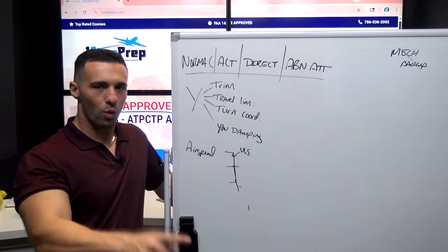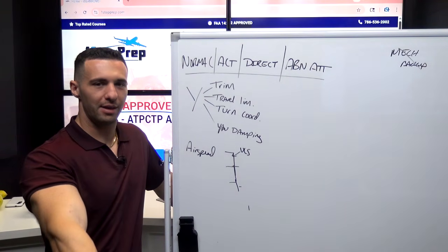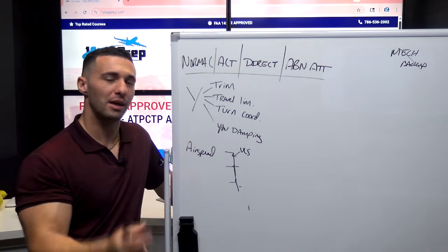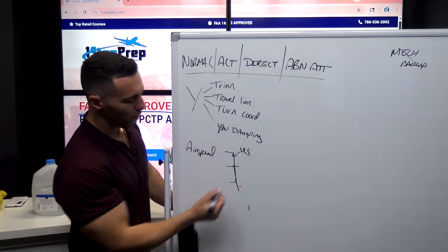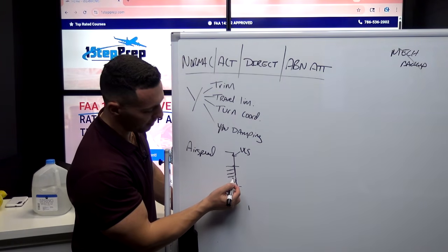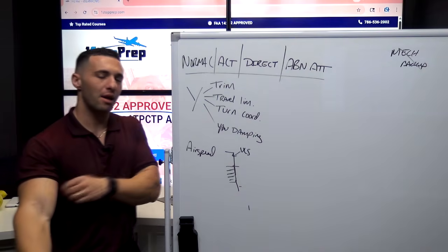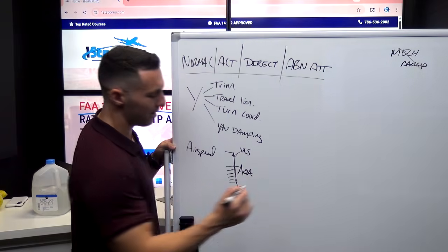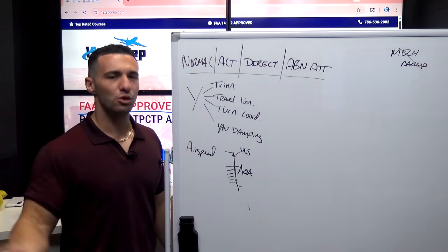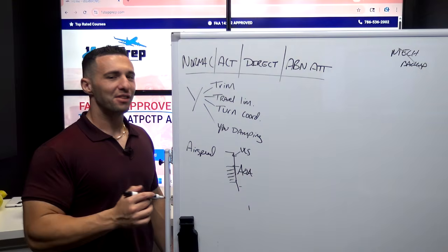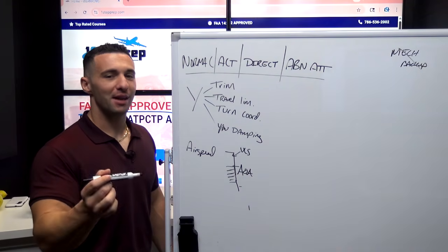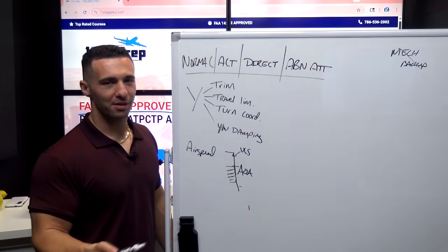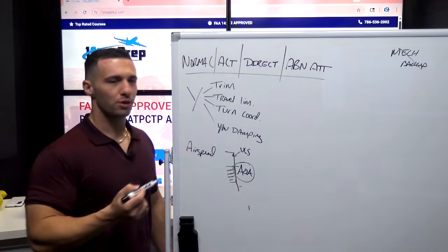So one is FMGC calculated down there, but the other one is a presentation being displayed by the FAC. To that degree, I want to share something else with you, which is that you also have alpha prot displayed here, which is kind of like these different dashed lines. And alpha prot, remember earlier I said that's the angle of attack where flight control computers intervene to prevent stall. It's not airspeed protection. It's not the airspeed where flight control computers intervene to prevent stall. It's the angle of attack where flight control computers intervene to prevent stall.